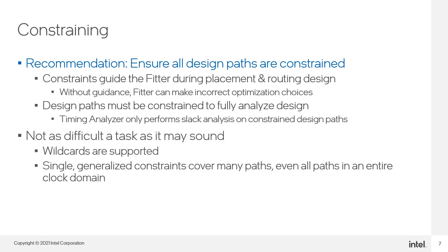The design needs to be fully constrained to guarantee proper functionality when operating in the FPGA. Since the fitter is timing driven, it will take the timing constraints that you have entered and place and route the design elements based on these constraints. Any constraints that are not entered or incorrectly entered will cause the fitter to make incorrect optimization choices. Timing Analyzer only analyzes paths of your design that have been constrained.